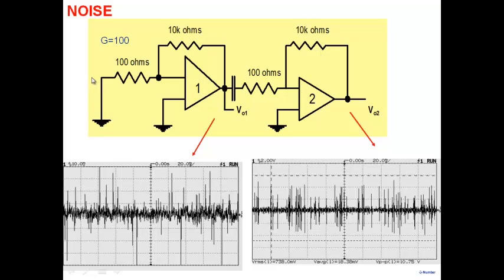Okay? So what it also illustrates is, when you have a multi-stage amplifier, let's say amplifier 1, 2, and 3, which amplifier matters the most in terms of noise? The first one. Because you see, this amplifier also generates 10 millivolt of noise. This also generates 10 millivolt of noise. But this one's 10 millivolt noise gets amplified by the second one, so it appears as 100 millivolt here. So the first amplifier is always the most important stage. Alright? So the first stage that we build, we have to build it as a low noise stage. We have to take special considerations in order to keep noise very, very low here.